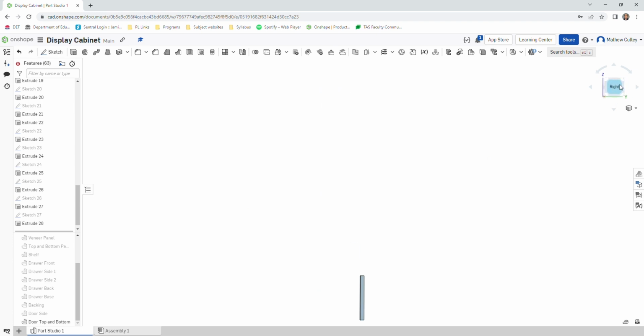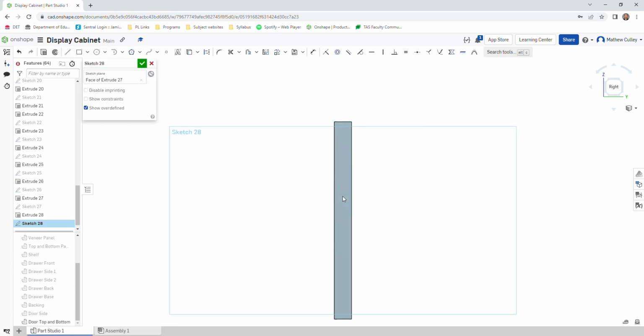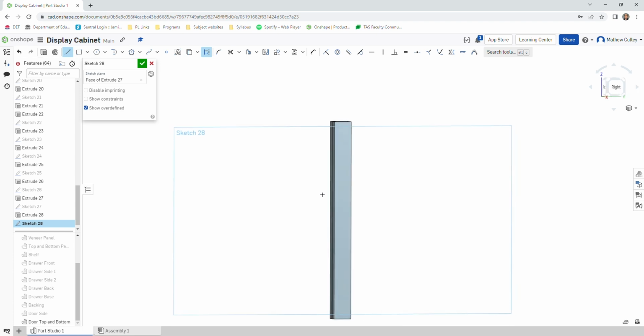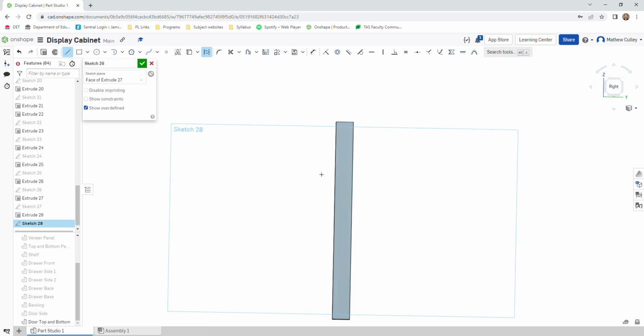Come around on the right face here, zooming in, select sketch again, select that face, L for line, Q for construction, making sure we are drawing on the same edges where our housing is. Left click once, come down, left click again, 19mm, enter, Q, so it goes to a solid line, come up to that corner, left click and escape, and repeat the process down the bottom here.